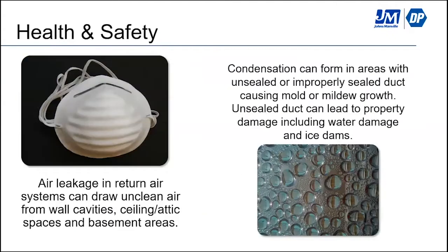Health and safety are another concern with unsealed duct. Air leakage in return air and sealing spaces in wall cavities can lead to infiltration. Basically, you don't want to breathe what's behind the walls and in the attic space. Unsealed duct can also lead to condensation. Condensation can lead to mold and mildew growth, and certainly a very big concern of building owners and occupants.